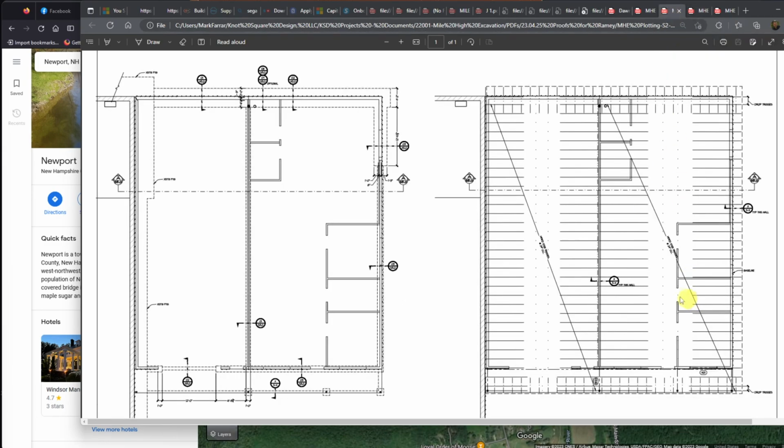Same sort of thing here. I draw all of the, in this case, we are looking at the foundation plan. This is the framing plan. We're right now discussing possibly pulling out a truss or two. And then I put in these detail bubbles. If you see, these ones have numbers because I've referenced them to the foundation details, but these don't have numbers yet.